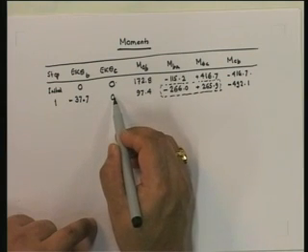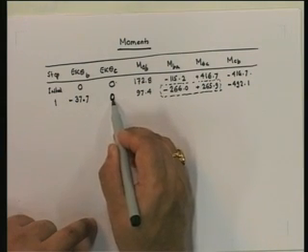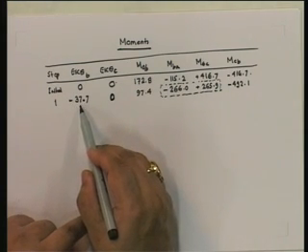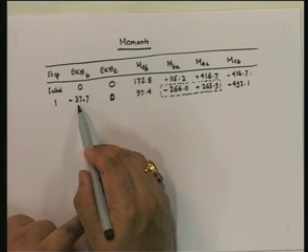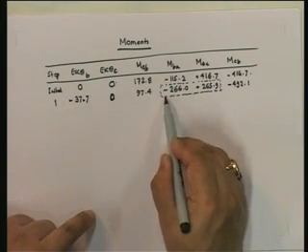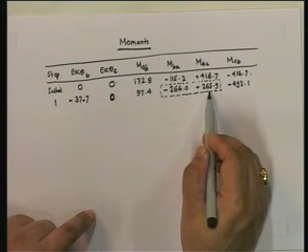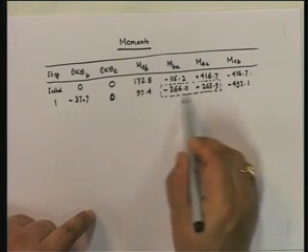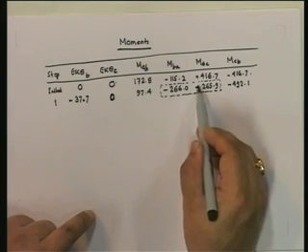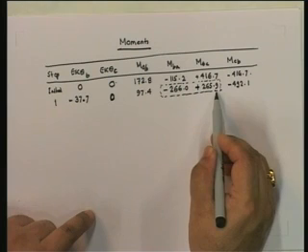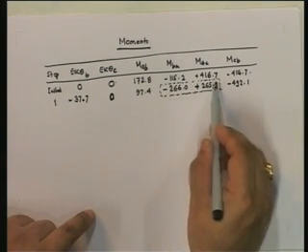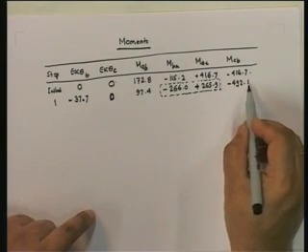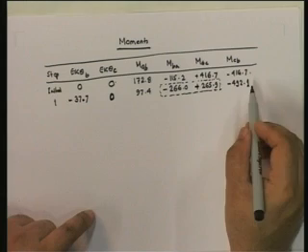I'm keeping theta C clamped and releasing the clamp at B so that theta B can occur. When I release the clamp at B, MBA plus MBC has to be equal to 0. So for all practical purposes, this is equal to 0. I have released it and made it equal to 0. However, MCB is not equal to 0. So next, what do I do?